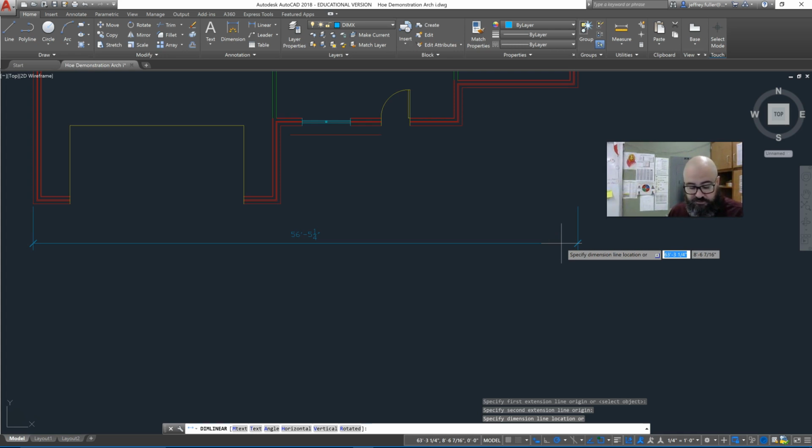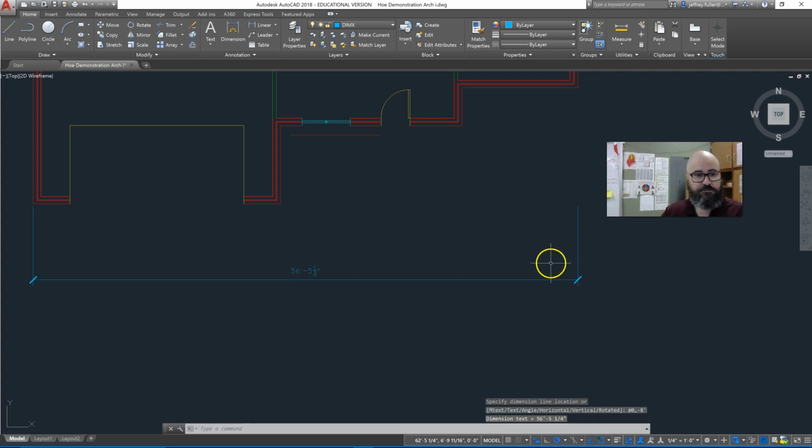So if I'm going to set this line at 8 feet away from the house, I am going to first hold the shift button and then click the @ symbol, just like you would do in an email or something. And of course that first box is my X axis, and I'm not going anywhere on my X axis, so this is 0, and then I tab over to my Y axis and type -8, and probably put foot on there would be a good idea. Okay, so now I'm 8 feet away from the house.